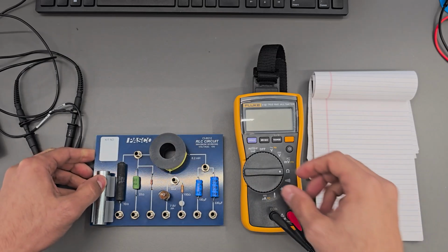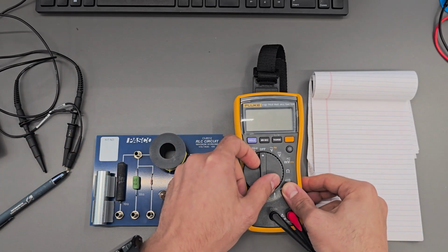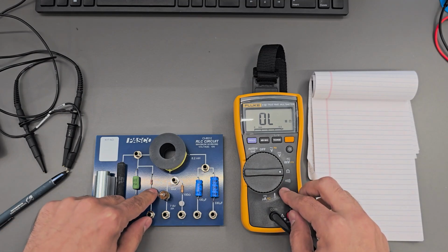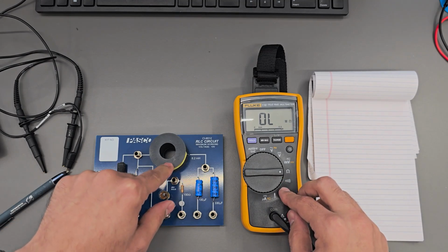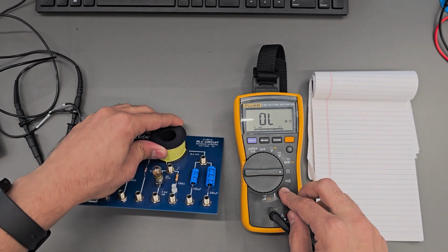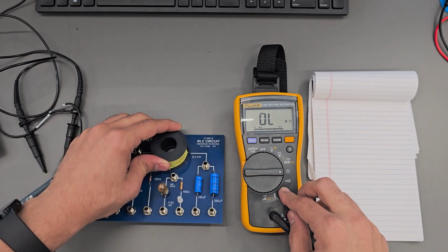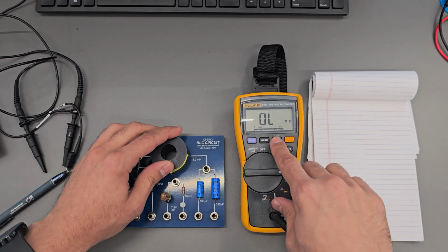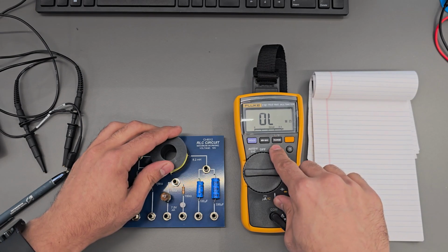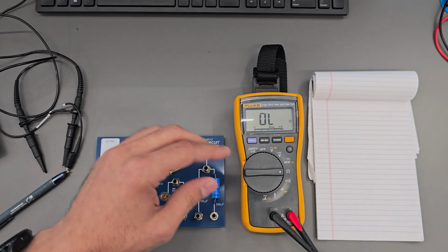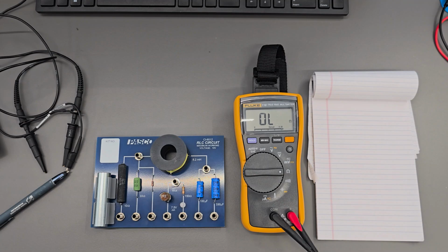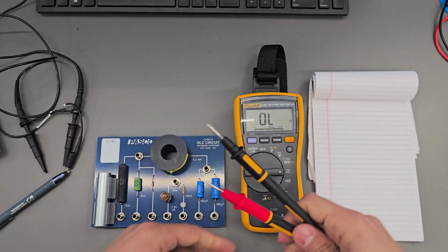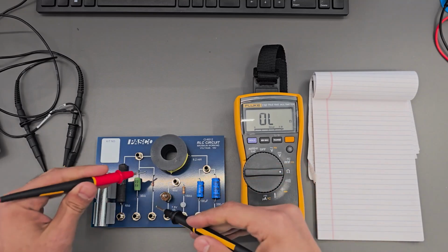Okay, so we will open the multimeter, put it on ohms, and because we know it's 100 ohms and this one is an inductor, so it's almost just a wire, a coil of wire, which means it has a very low resistance. Let's reduce the range here and make it ohms only, and let's get the probes for the multimeter. We have it here, so let's measure.